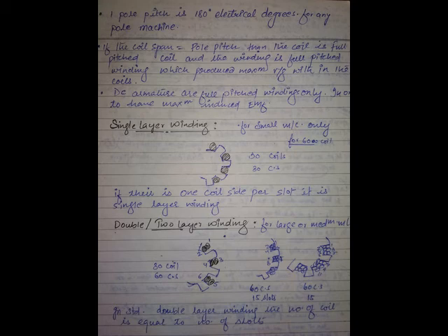The remaining conductors will be 2, 4, 6, 8, 10, 12, while this set is 1, 3, 5, 7, 9, 11. Let these 6 conductors make one more set. So how many sets are there now? 2 independent closed sets of windings. If you connect them in series, all the 12 conductors are in series, right? So you get the same format. If you connect them in parallel, then comes the difference.